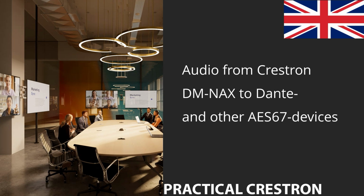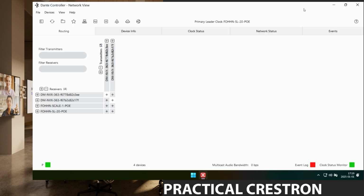In this video, we will have a look at Crestron NAX and how we can send any audio source to any receiving Dante or AES67 device. For this, I have set up a couple of Crestron devices as audio sources and two Fohhn Dante speakers. To demonstrate, I will be using Dante Controller, a program that can see and handle both Dante and AES67 audio.